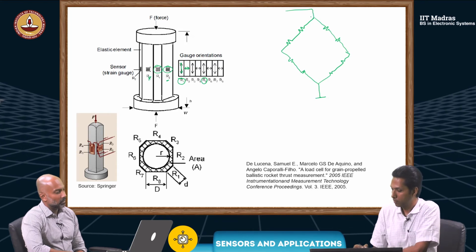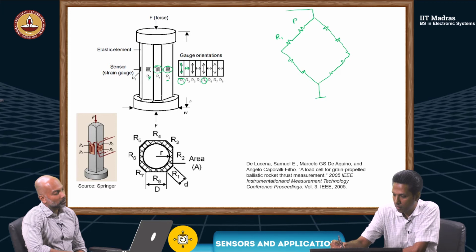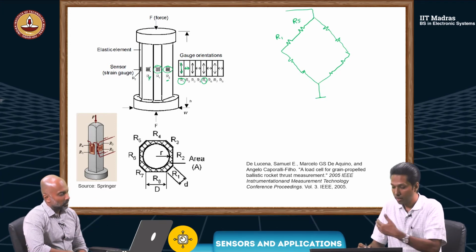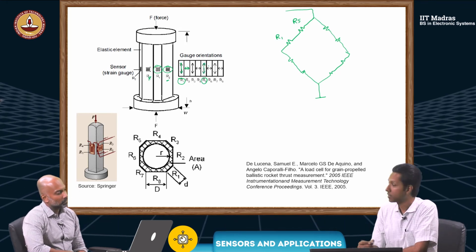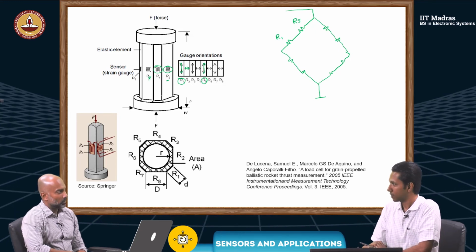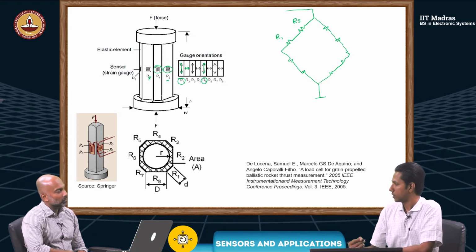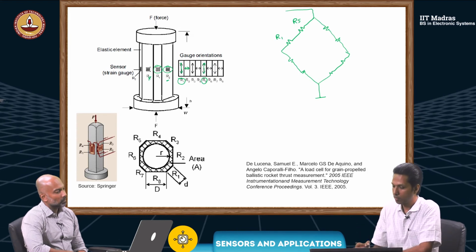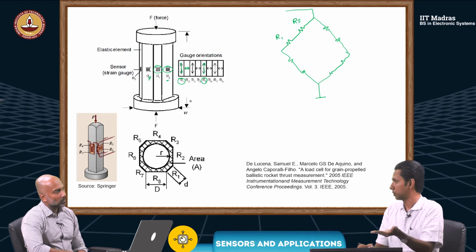They are in series. Yes. So maybe I can keep R1 and R5 in series. And they're in opposite directions. Oh, they are anyway in same, sensitive to strain in same direction. So it can get add. Okay. Correct. If you have it in series, it will add. Yes. So it's like R1 and R5 together giving a change in resistance. Okay. So when there is compression, there will be reduction in resistance. It will happen to R1 and R5. Correct.